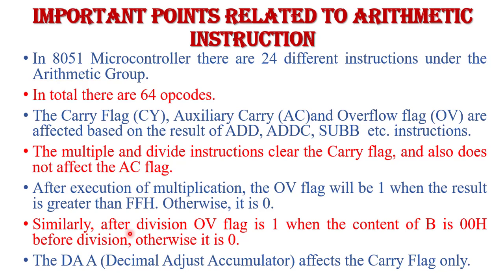Similarly, in division, the overflow flag is set when the content of the B register is 00H before division, otherwise it is 0. The last point is that the decimal adjust accumulator, that is the DAA instruction, affects the carry flag only. So these are some important points related to arithmetic instructions.